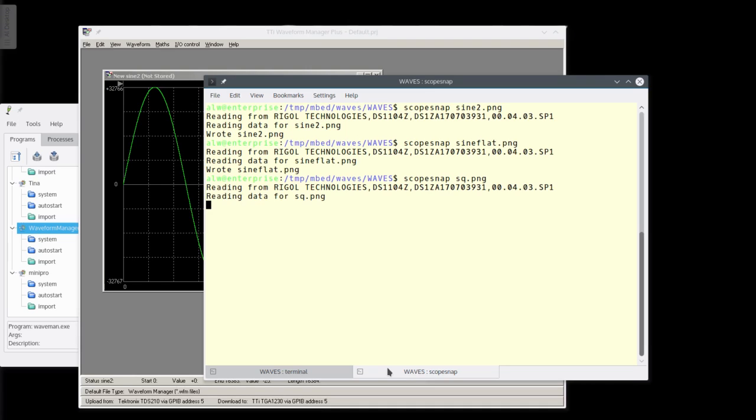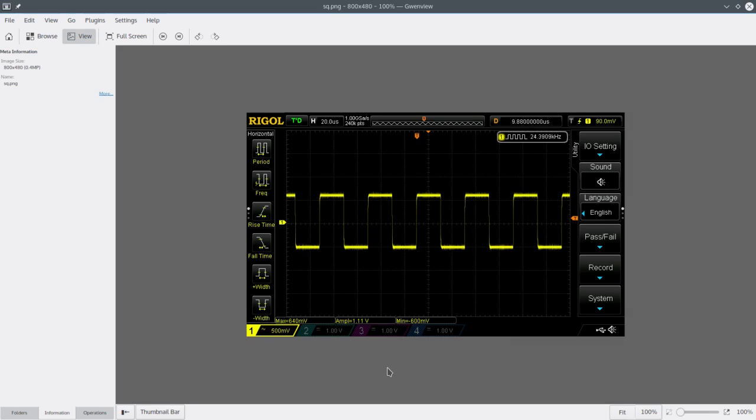We'll load that from the scope. And of course, naturally, they didn't line up on the graticule, but you can see that's 20 microseconds, and that's about a graticule across there. So each step coming out of the buffer is 20 microseconds. And again, that's because of the calibration curve fit that I discussed in the post.